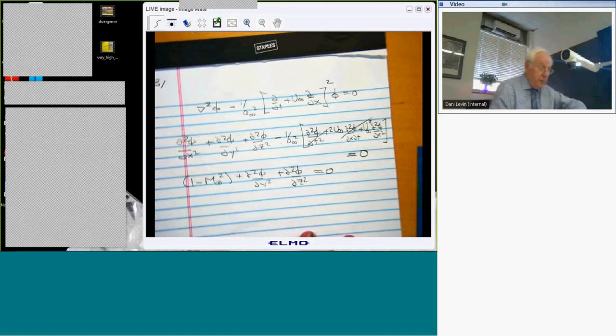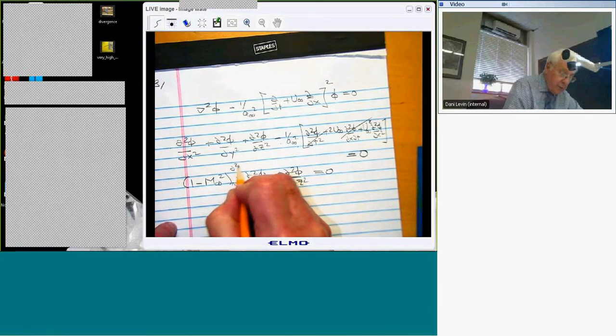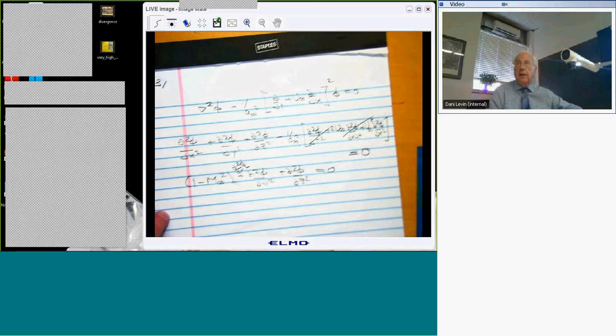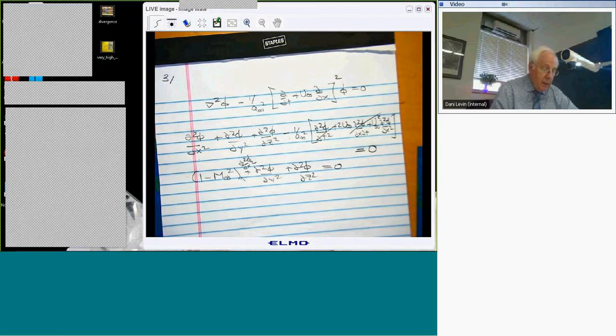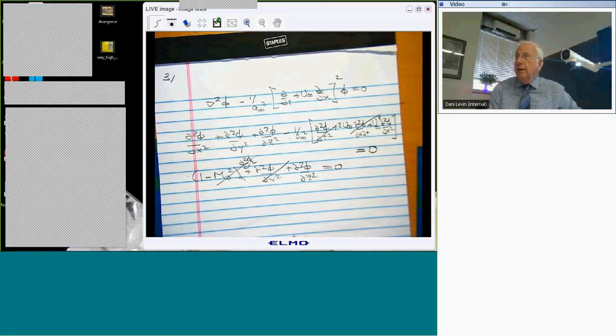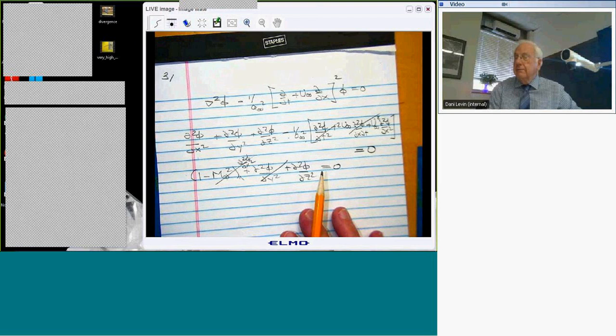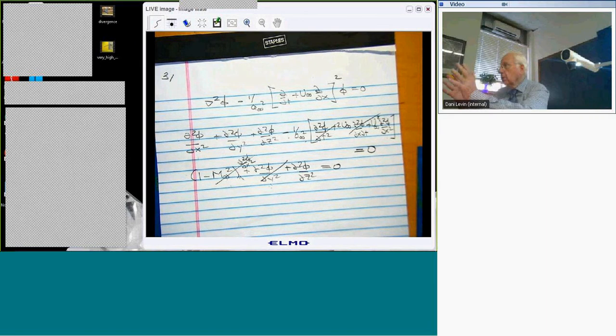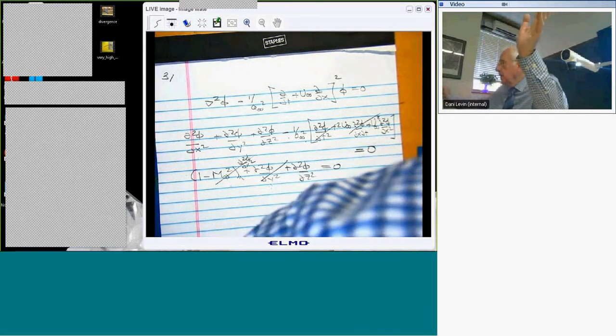Oh, I left out something. It's really important, right? Sorry about that. Now, when the Mach number goes to 1, that term goes away. If I were in 2D flow, that term wouldn't be there either, and I would get a degenerate model and it's just useless. If the flow is highly three-dimensional, so this term is really important compared to this term, that's a low aspect ratio wing, right? Where the chord is large compared to the span.